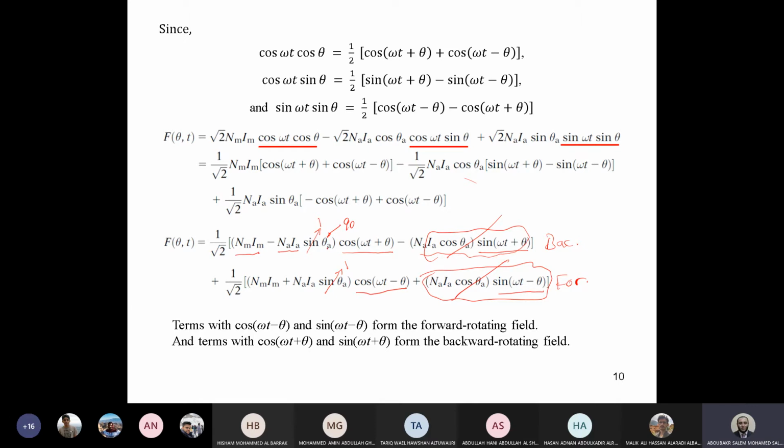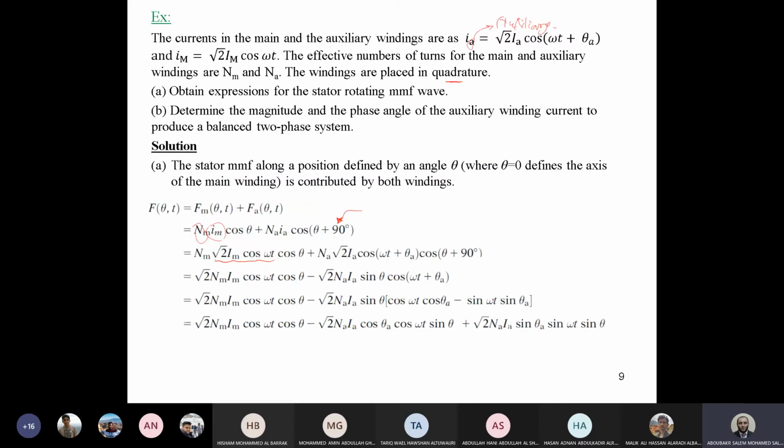90 degrees means theta A equals 90 degrees. Again, what is theta A? Let's return to the definition here. We said that theta A is the angle of the phase shift between the two currents, which comes mainly from the ratio between the reactive and active parts, or the resistance and the inductance, of the auxiliary winding. Okay.